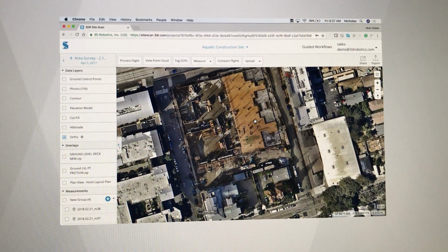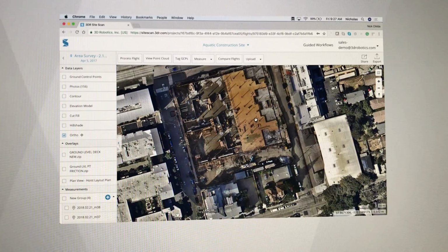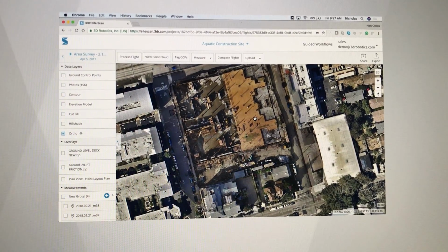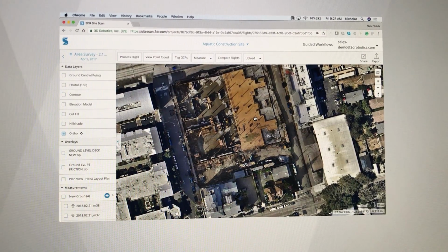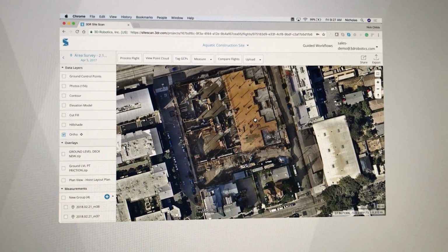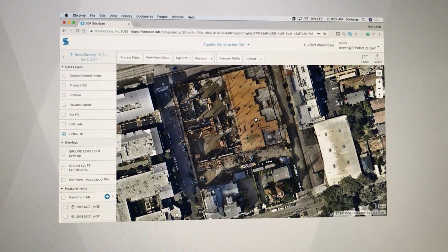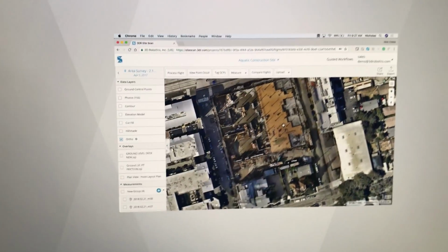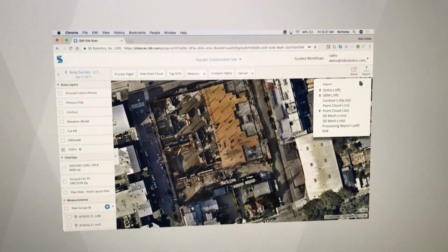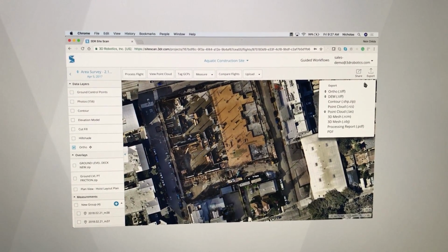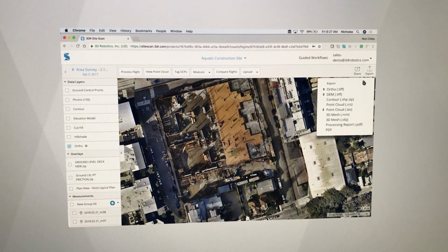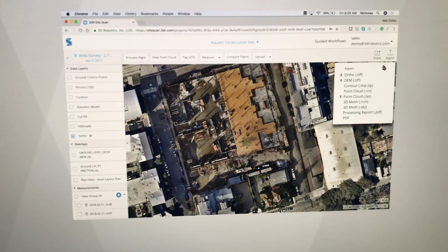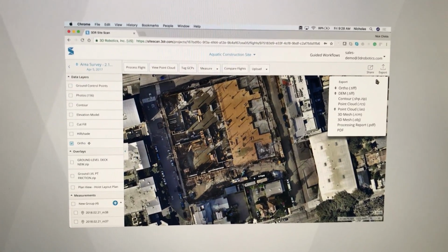But essentially, you could bring it into Recap and edit the point cloud. We're producing the file format directly, so there's no conversion. You can open it all up from Recap, because on the back end, when we process this data, it's going into your A360 account. So you don't even necessarily need to come into SiteScan. You can just open it up and edit it there.